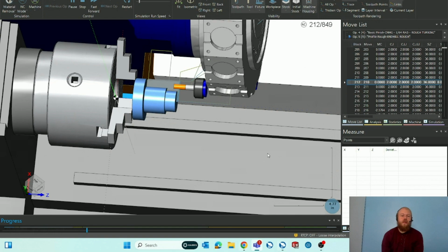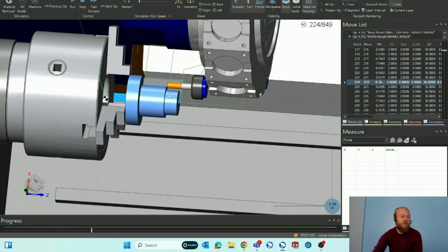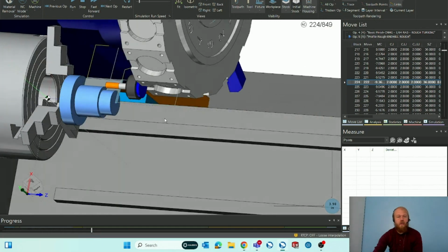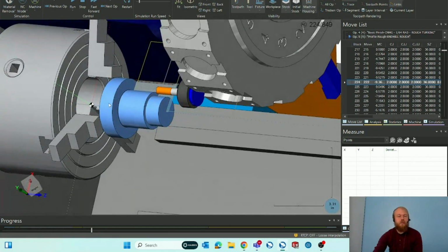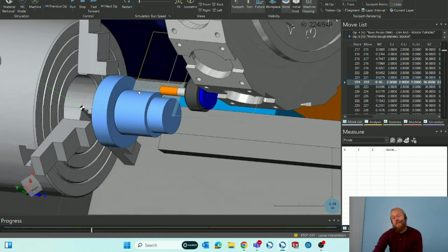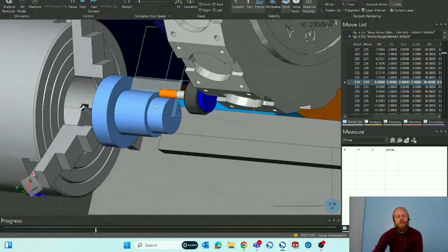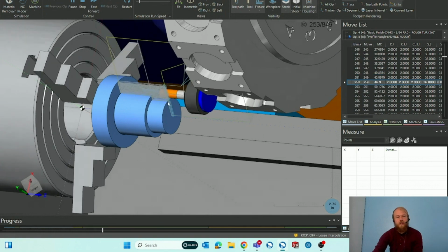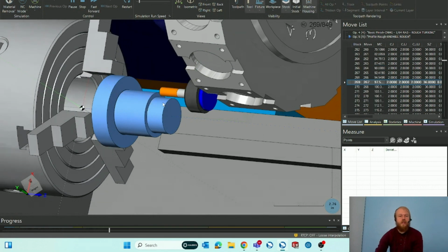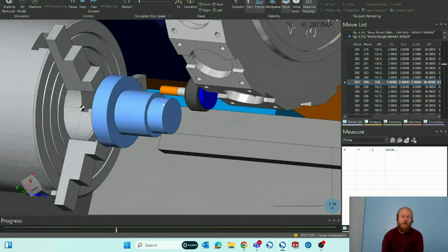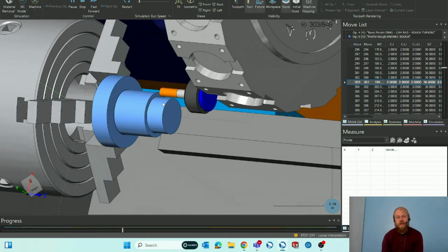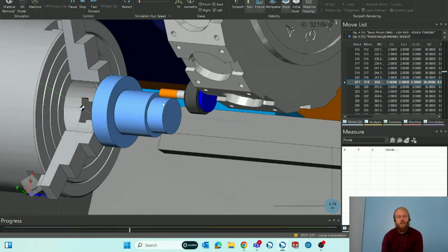And then it does the milling on the hex. Now you can see the tool isn't going to move in X and Y around the part here. And the reason for that is because this machine does not have a Y-axis movement capability. It does have X and it does have Z axis capability. So it's coming down in Z to the total depth here. And then it moves back and forth in X. You can see the coordinates right here, back and forth in X like that, inside to outside. And the part rotates around the C axis to give us this hex here once it starts cutting eventually.